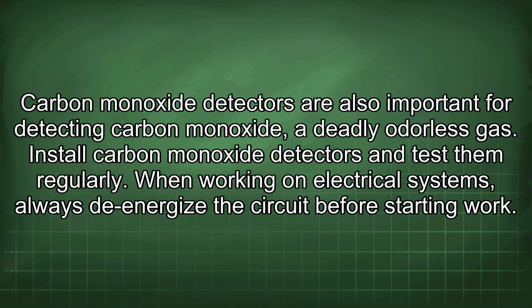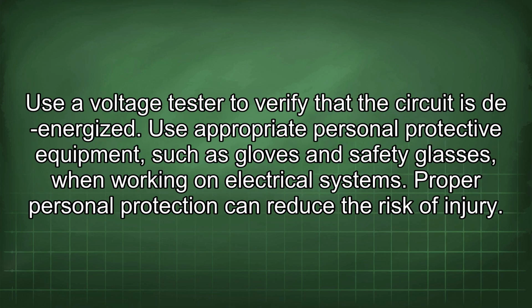When working on electrical systems, always de-energize the circuit before starting work. Use a voltage tester to verify that the circuit is de-energized. Use appropriate personal protective equipment, such as gloves and safety glasses, when working on electrical systems.